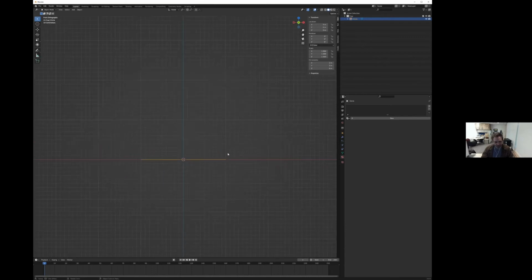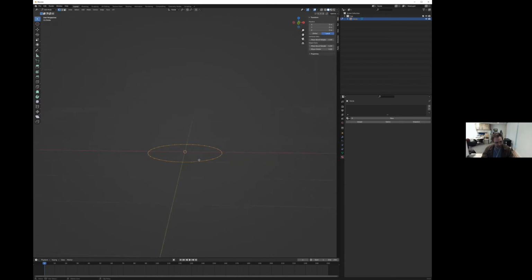What does a cup look like? So we have our base, and it's a very simple design. Let's select the edge. So we have that selected in our edit mode. You can either click and hold Control and go around, or you can hold Alt and click. So now you have all of the vertices and all of the edges selected.